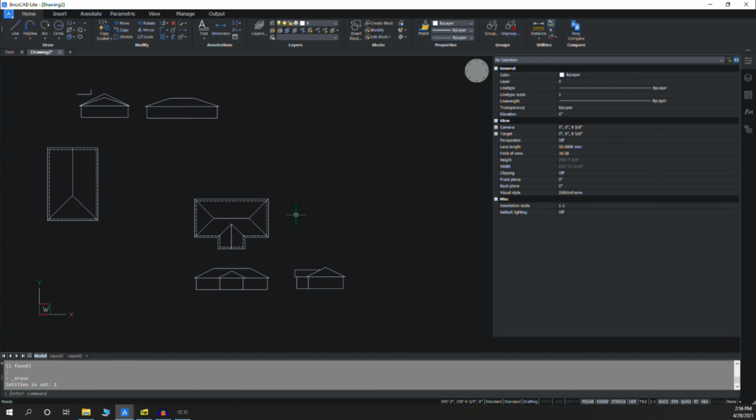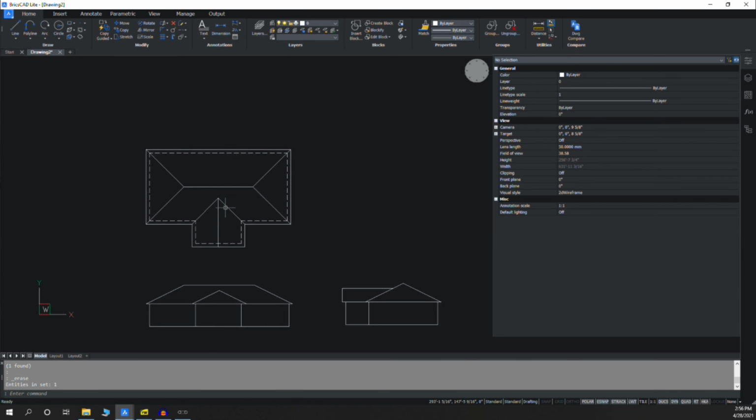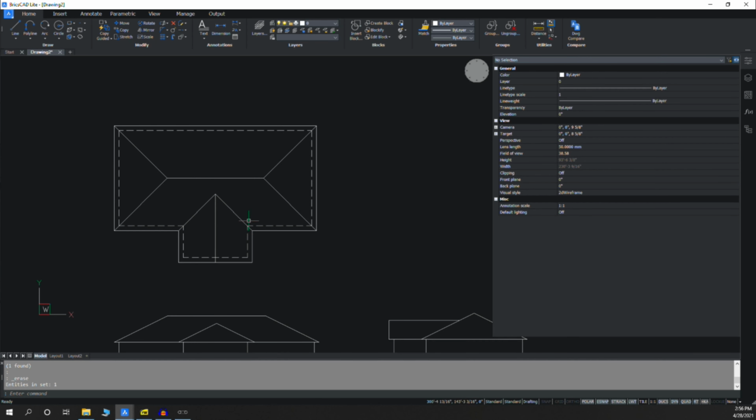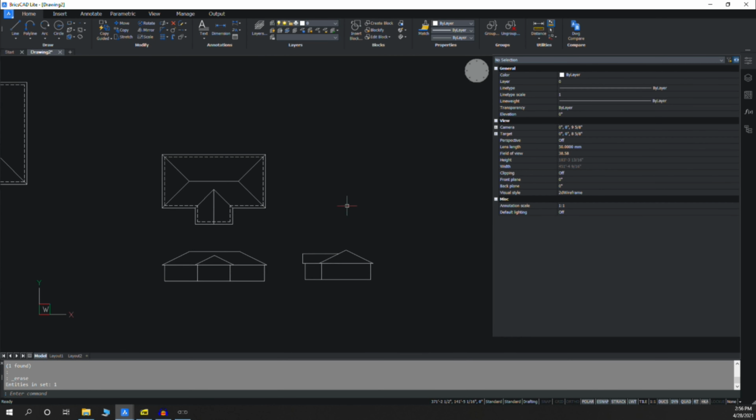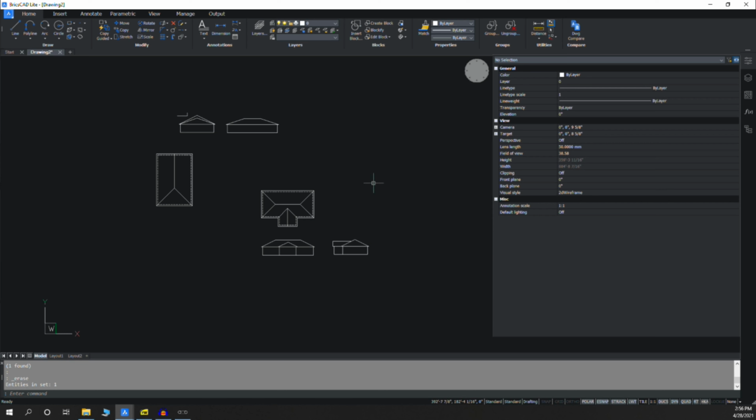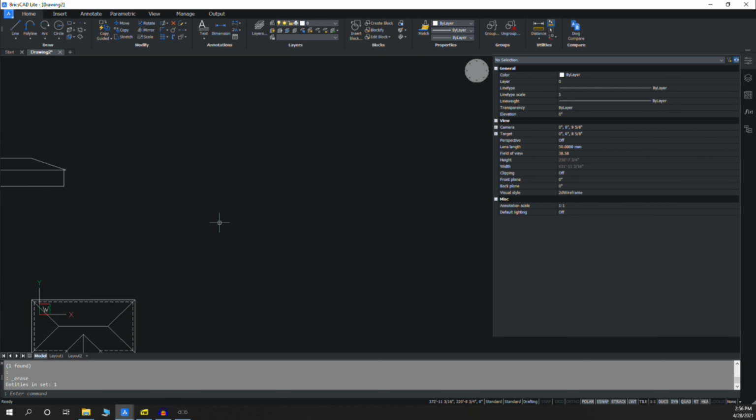My house in particular, the one I'm designing, has this front gable here is an 8/12 pitch, and then my main roof is a 6/12 pitch. And those same techniques for figuring out the roof pitch totally work, but for figuring out the pitch of the valley, you actually have to be a little more careful. So I'm going to draw up another sample house really quick, and we'll explore that.